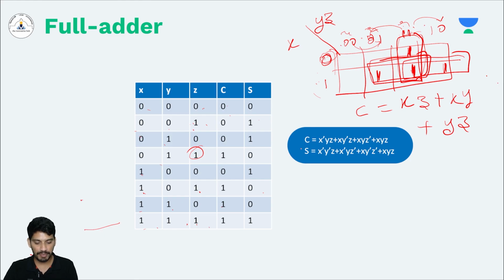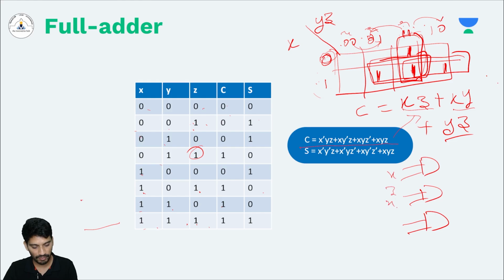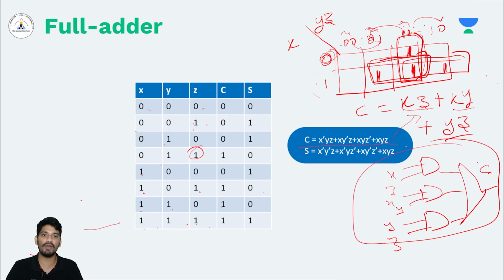See, this big expression is reduced into a very small expression. Now you will require only three 2-input NAND gates. You will get xz, xy, yz, and then sum these using an OR gate. That is one way of achieving C, right? Yes, so we have simplified C.